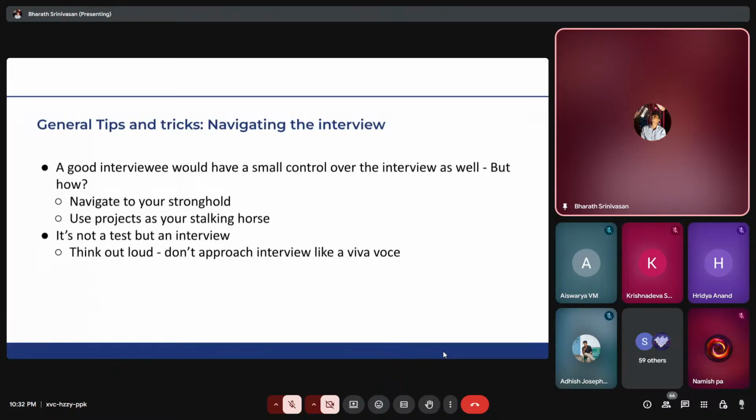Basically, what I do is that I tell them what my steps are. So they gave me a question, like, Bharat, can you give me a divide by three frequency divider? And I will go like, okay, you have got this. So this won't be just happening in my brain. I'll say it out loud to the interviewer. So you have the first flop, the second flop, and a logic that controls after three flop cycles that will reset all three flops or something like that. All right, so you just need two flops there.